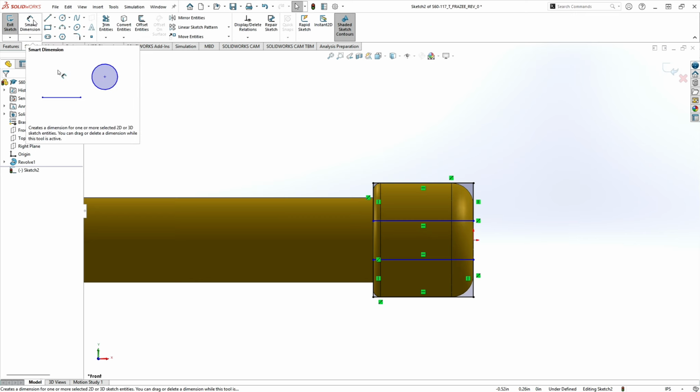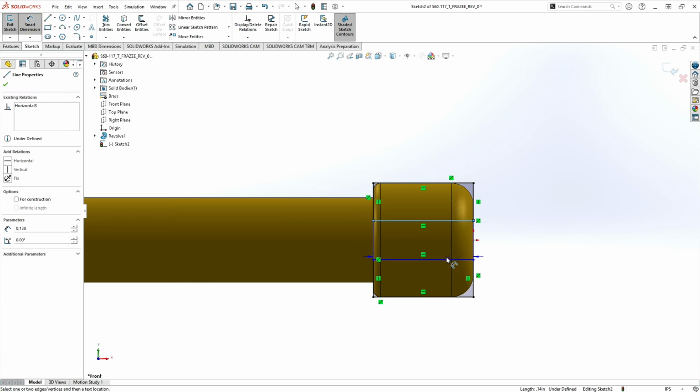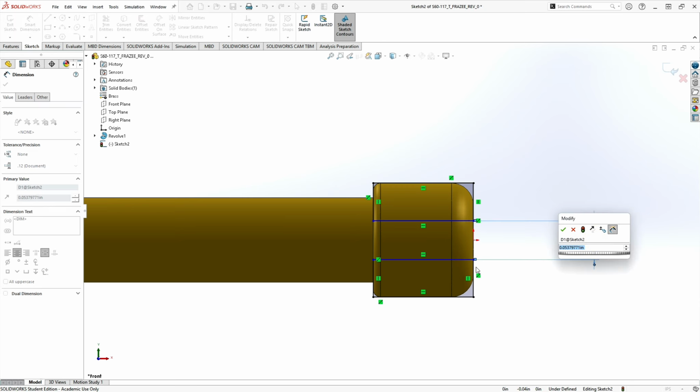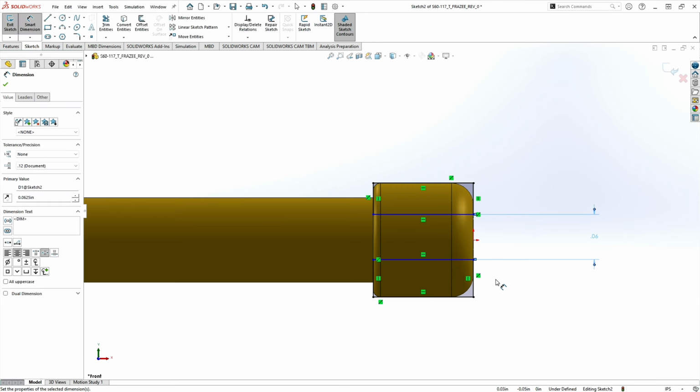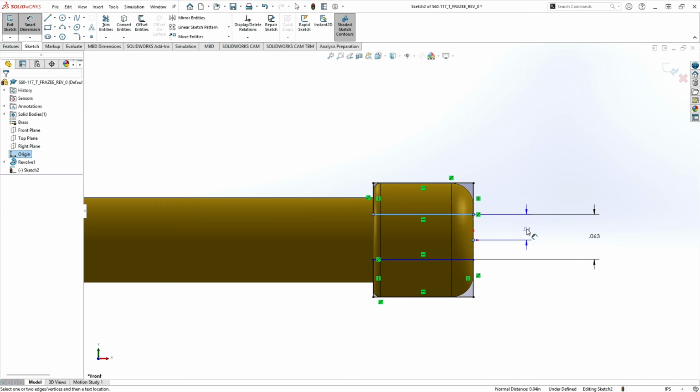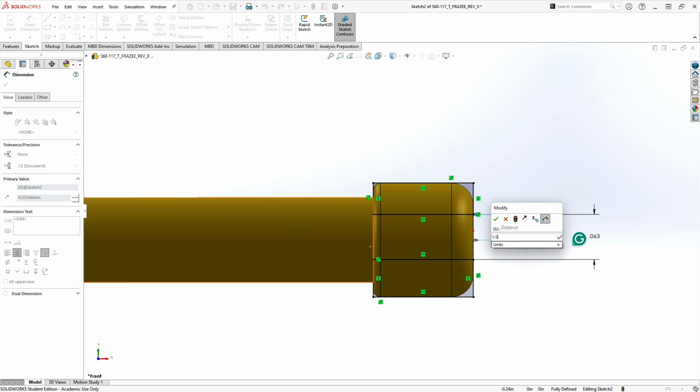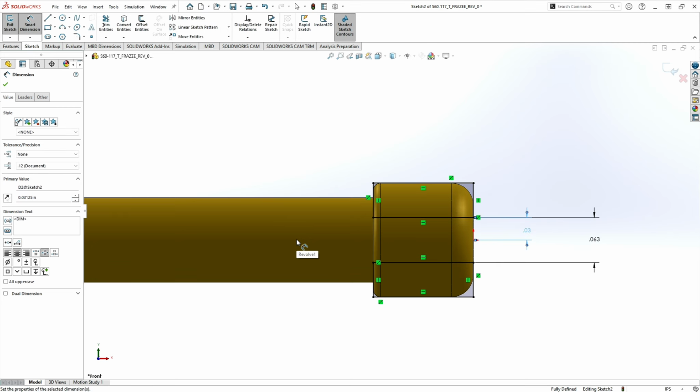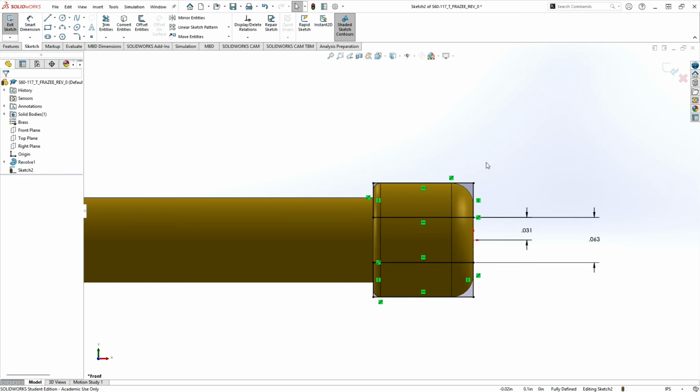Okay, so we can go from the width, let's put that in first, and we're going to put in 1 divided by 16. That gives our 60 thousandths, but if we go up to 3 place decimals, it's 63. Then we're going to go off center line to center, and type in 1 divided by 32, which centers the feature, but at the tolerance we're working at, it doesn't exactly reflect it. Okay, so at this point, this should be fully constrained.